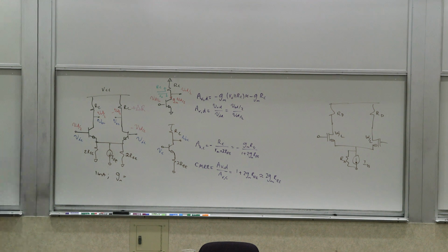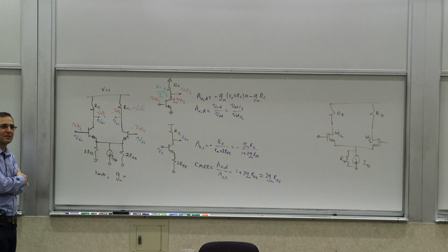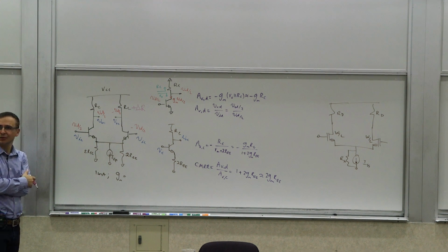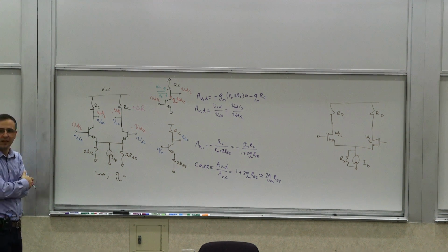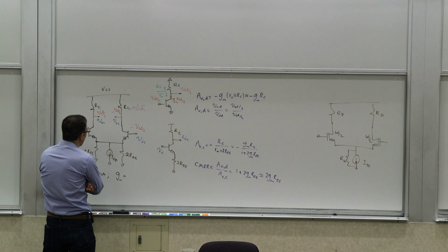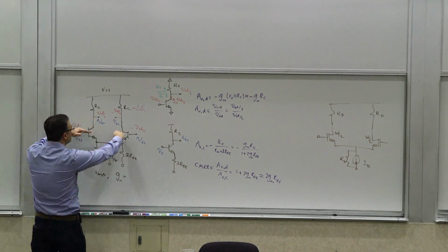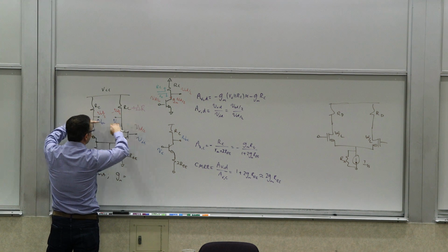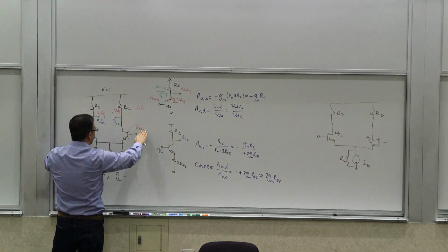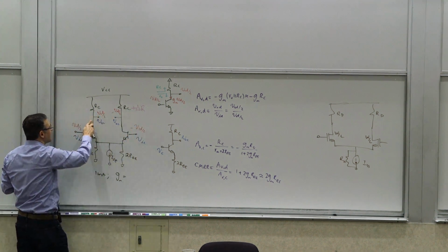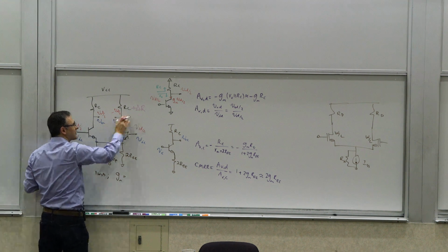Let's make that, right? So if you have something like this now, let's say one of the resistors is slightly different. Let's see what happens. If you have one of the resistors that's slightly higher, then on this side, from the input perspective, if the early effect is not strong, you're still seeing the same behavior, right? But from the output, the same current would produce a different kind of output.